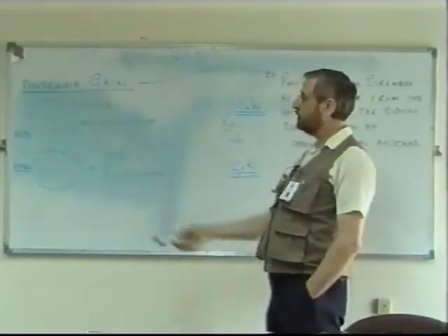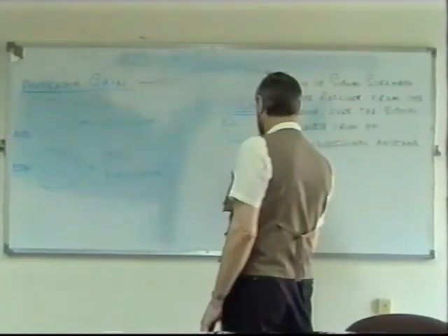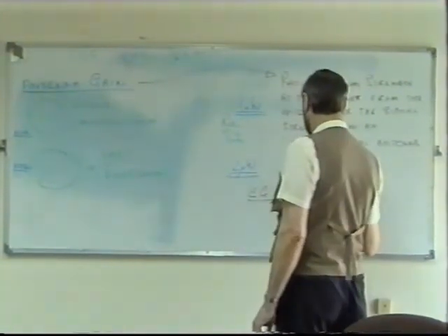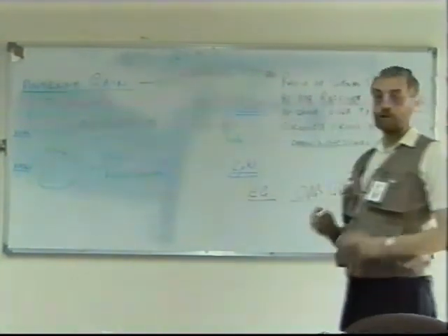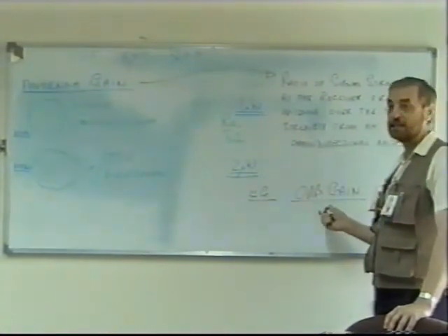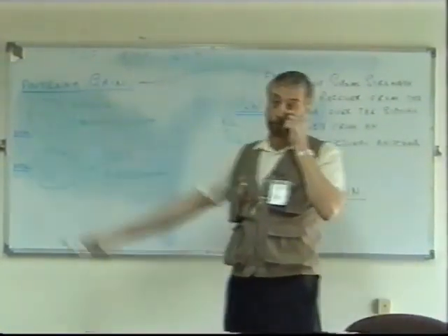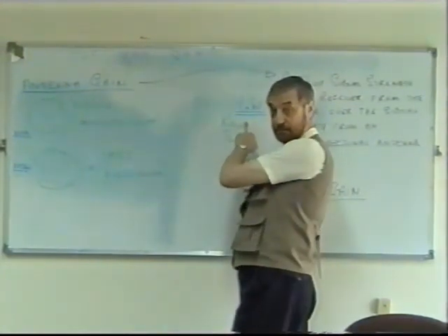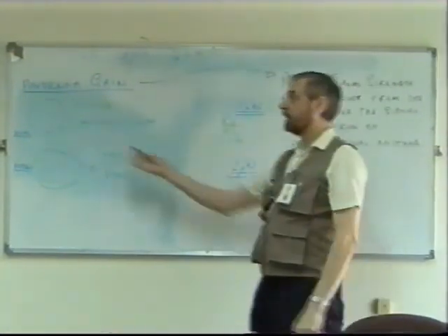So if somebody says to you, I've got an antenna with a 0 dB gain, you know that the output from it, whatever shape it is, will be the same as from a dipole. If you put a receiver a certain distance away and measure the strength of the signal at that receiver, it'll be exactly the same from the antenna you're talking about compared to a dipole.